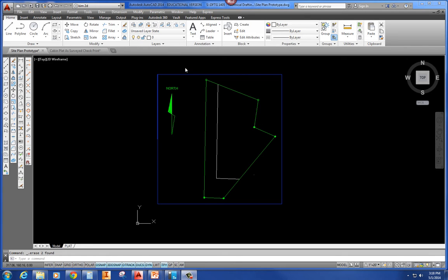Okay, we're getting ready to go now, and I'm going to show you guys how to draw the house plan, as well as offset some lines and make sure that you have the house aligned to the correct offsets. Essentially you're going to have some dimensions offset here for 2 points on the house and offset this way. So I'm going to use offset.